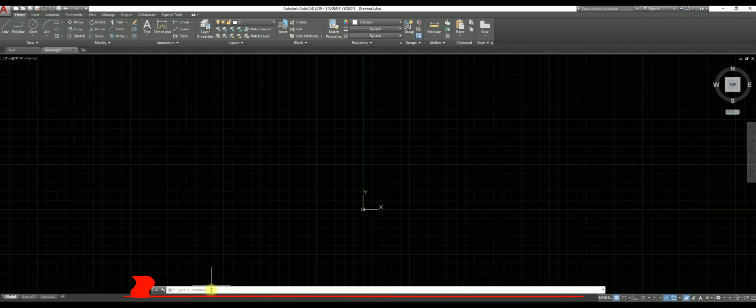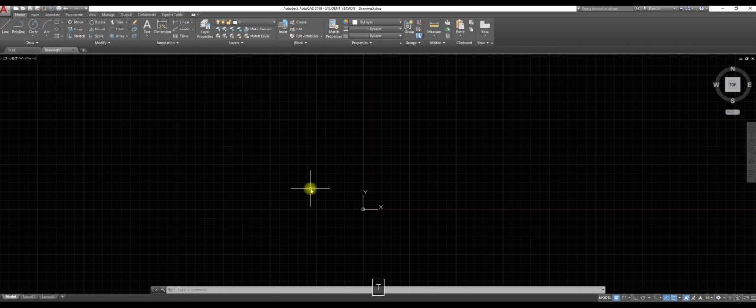Next, my favorite is the command prompt. Anytime you're typing in a command to AutoCAD, let's start with text, which is one that I like. The command prompt tells you when you're in a command, it tells you if there are more options inside the command, and it tells you what settings are current. So current text style is Standard.